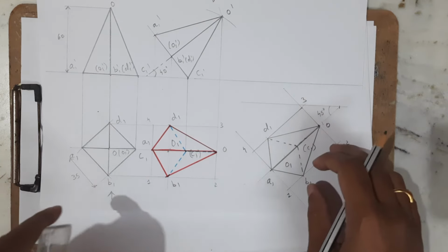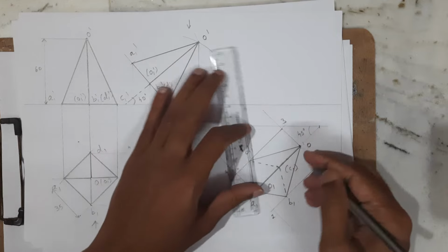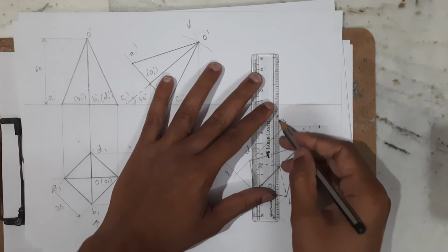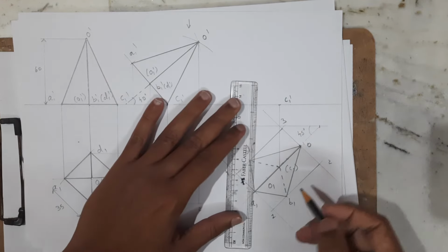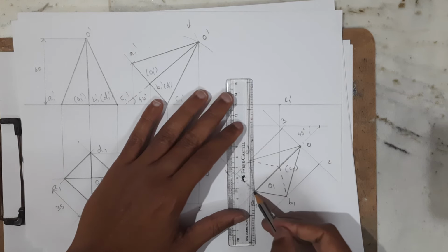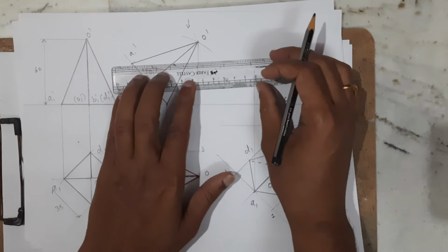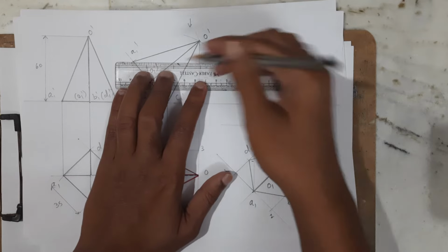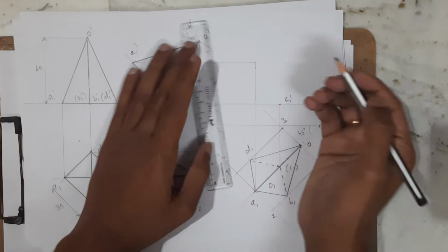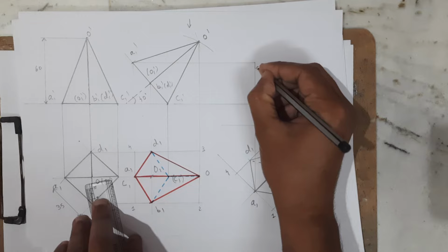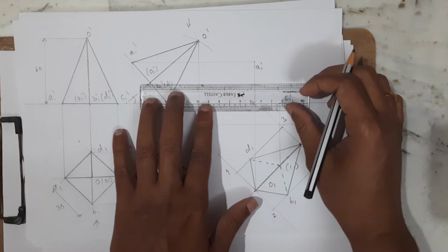Now with the help of this top view, we need to draw the front view. How to draw it? So we have to draw the projection. So let me draw from C1 until it touches the XY line. So this is the projection of C1 dash, right? C1 dash. Next, draw the projection for A1 dash, vertical projection upwards, and horizontal projection. So this is A1 dash.